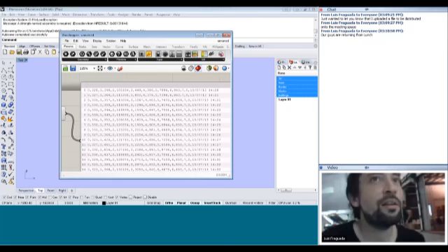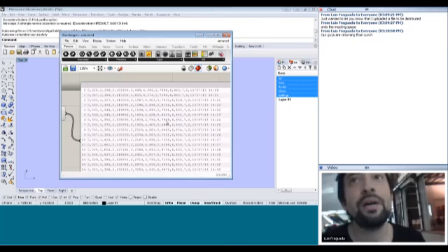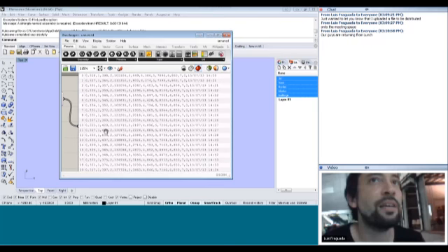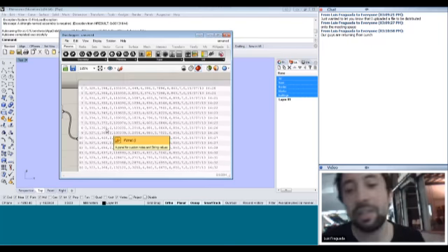Well, every other column is the sensor ID, and then in between there are the values of the sensors. Now, the way that we have them set up, they're just set up as integers. So, for example, if this is temperature, the first thing, we have to divide it by 10 to get the 32.8 or 32.7.